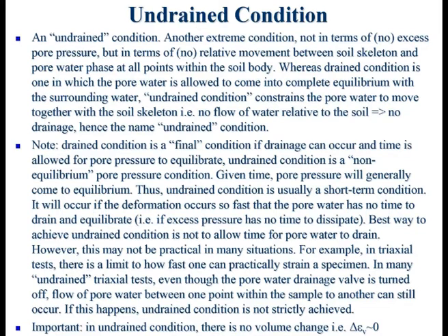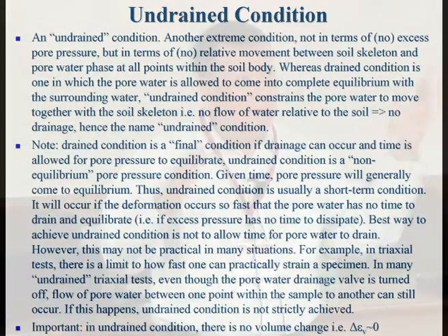You know? So usually the authority will say, okay, you don't want to do that, fine. You run one undrained and one drained. So one is the very short term, one is the very long term. If both are safe, I kind of assume that somewhere in between you should also be safe. You know what I mean? That is the basic assumption. So basically, the baseline is to run one drained and one undrained, or one undrained and one drained.